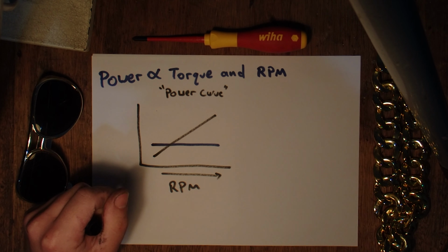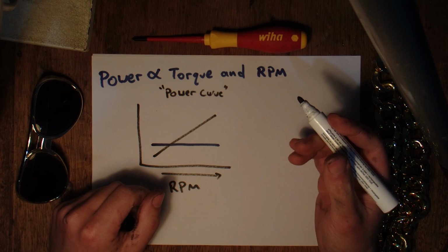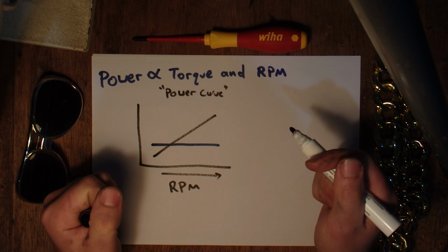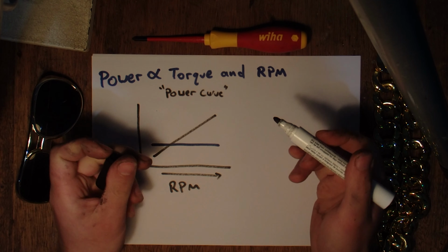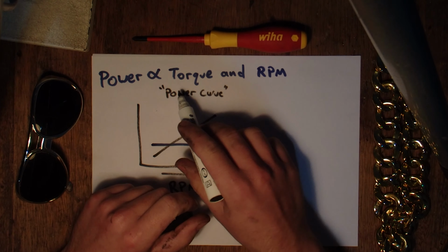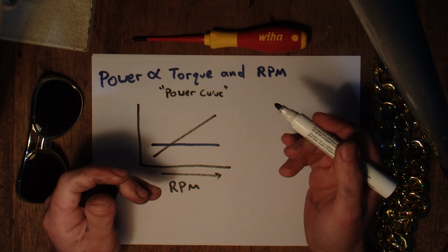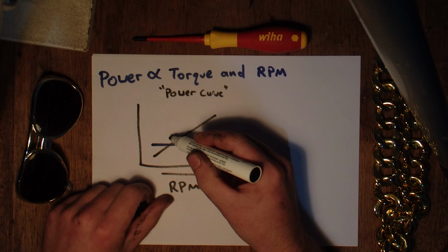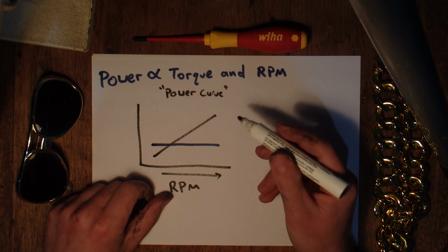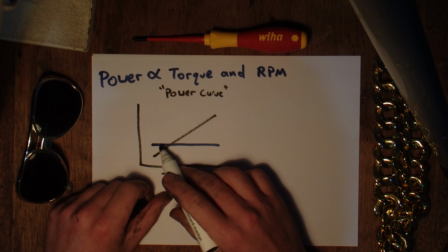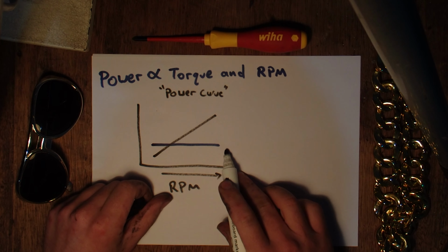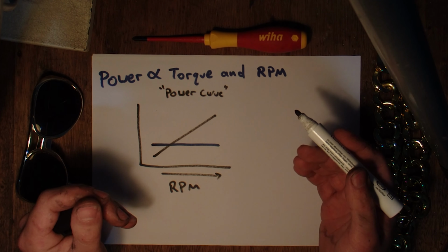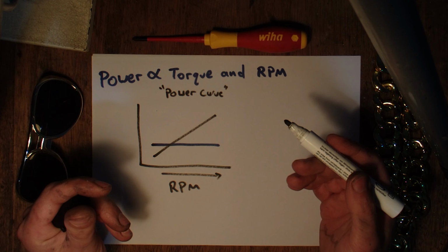So the confusion that gets thrown around a lot is, torque does something and power does something else, and I've got a really torquey motor, and that's all great. That can be a way of describing how an engine delivers its torque. Your really large capacity engine might have a lot of torque on the lower end and then less up top, whereas a smaller capacity engine might have less torque overall, but a really consistent amount of torque throughout. And they do change the characteristics of how it drives, in the case of a vehicle.